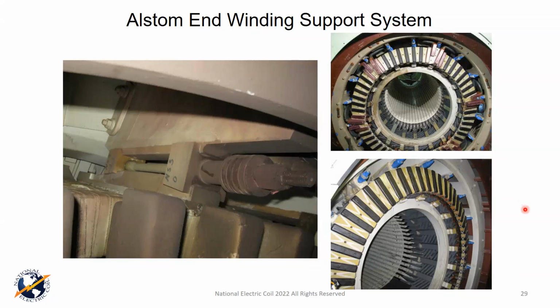But this bump test is something I'm hearing for the first time, that this needs to be tuned as well to resolve this issue. This phase break failure is so severe that if it happens at the bottom side, it also hurts the rotor badly. That's what happened to us actually.